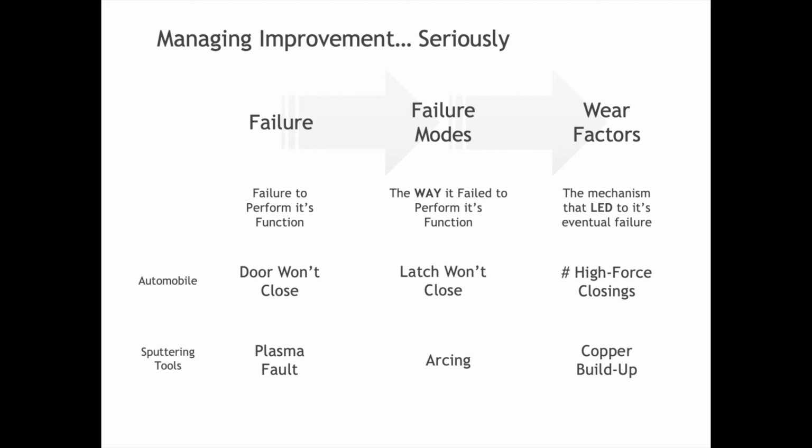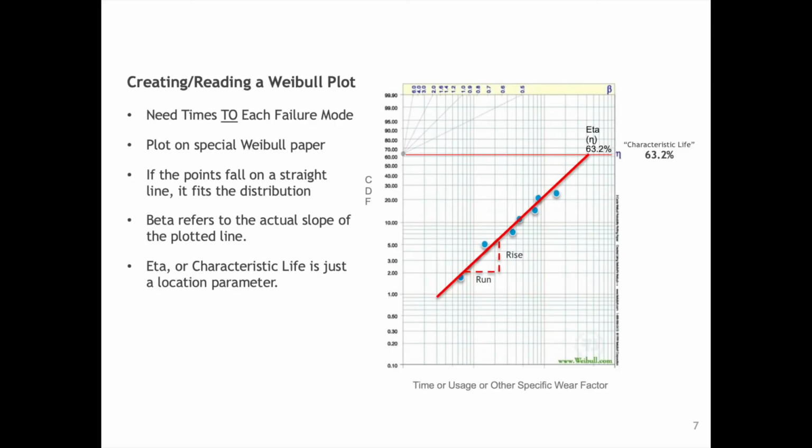We need to go further to failure modes, that is, the way it failed to perform its function, like latch won't close, and then look at the wear factors, which refer to the mechanism which leads to the eventual failure mode. Perhaps the number of high force closings.